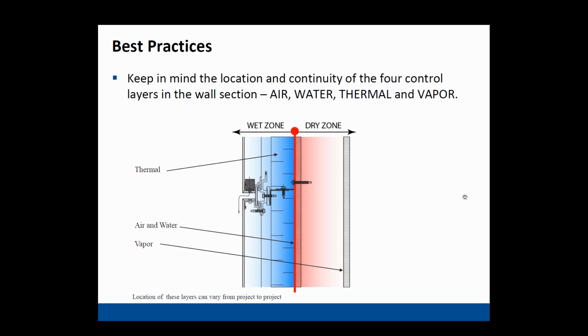When you're dealing with a back ventilated or a pressure equalized rain screen system, you're dealing with a system that's made to get water inside, it's made to not be perfect, and it's made to get the water out. There's a certain logic to that. From the get-go, your sealant might not be perfectly installed, and you've got infiltration. This other system gives you redundancy. It gives you ways for it to self-correct, whereas a barrier system does not. So I know our office in particular would promote going with a rain screen type system. That being said, each situation is going to be somewhat unique, and there might be places where a barrier system is more desirable, but you'd have to look at it on a case-by-case basis.